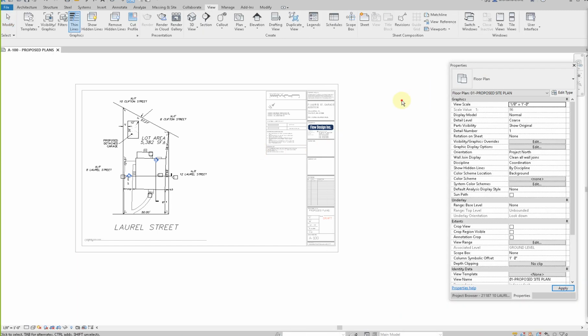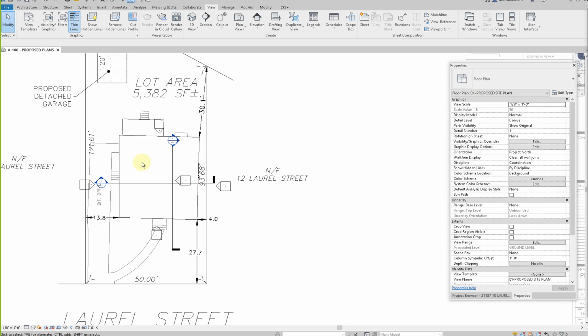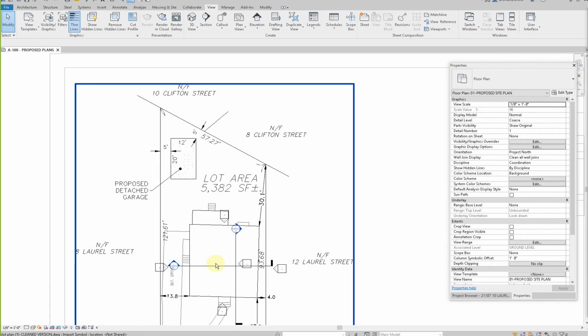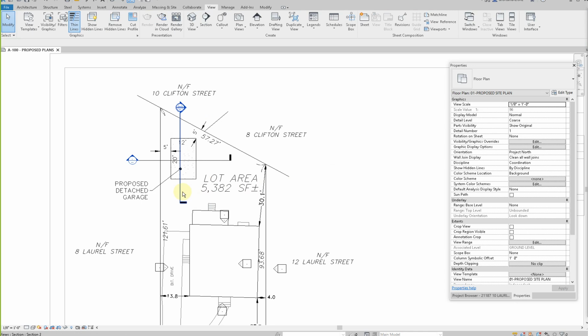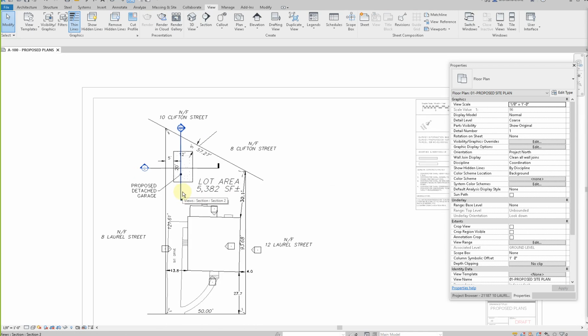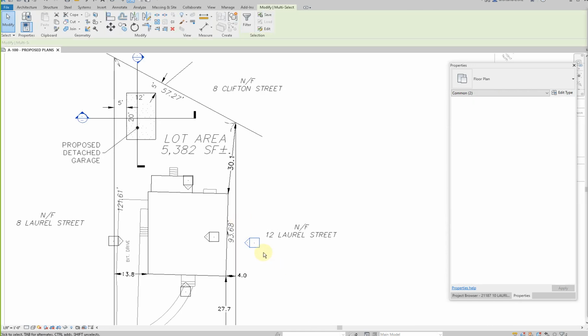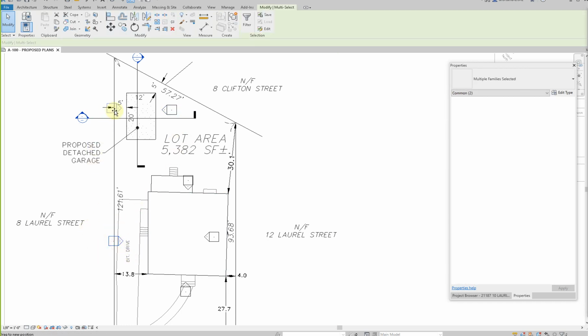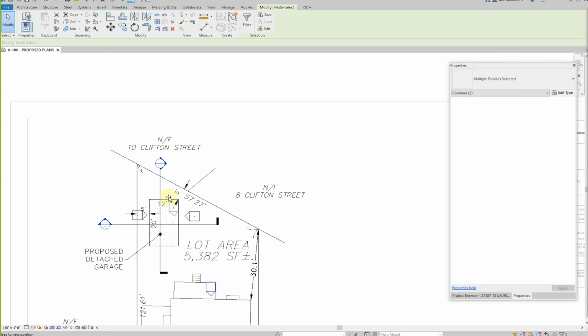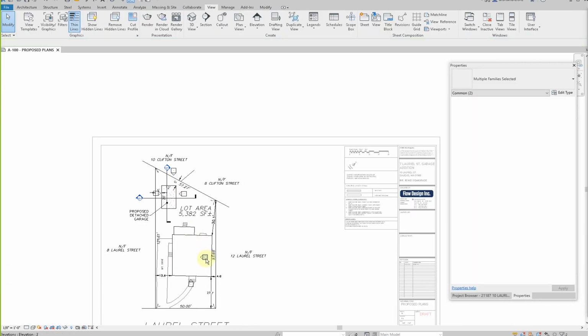So, all right. Because I changed the facing, then all this ugly stuff showed up. Well, it's not really ugly stuff. You're going to be needing sections eventually. So drag it on the right place, because you're going to be cutting a section there, and you're going to be cutting a section there. Now, you don't want to see it on the site plan. You don't see section cuts on site plans, okay? There may be an occasion in which you would, but right now, just trust me on this one. You won't want to see it. But I would drag them where they go, so that at least they're referring to the right stuff. And I'll explain that later. Drag them where they go,